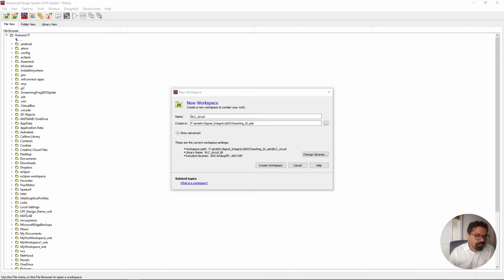So having said that, one of the key features of being a good electronic designer is, first and foremost, there's no substitute for actually making these things. I think that's still a very important criterion if you really want to be really good at it. But another thing is, before you fabricate the board, it's not a bad idea to simulate some of the concepts or simulate the performance of your board, using a 2D field solver or a 3D field solver, understanding what are the possible issues that could arise, be it signal integrity, be it power integrity, be it EMI, or whatever you're exactly trying to test.